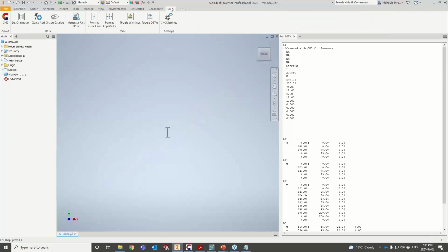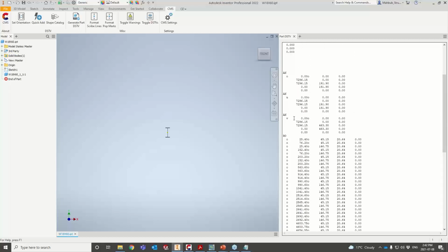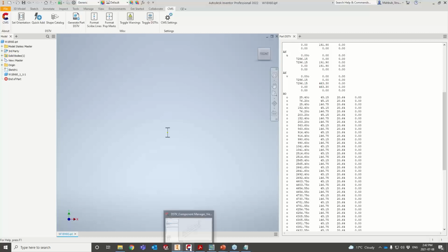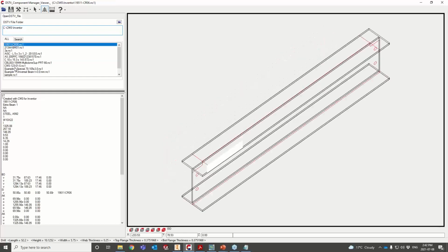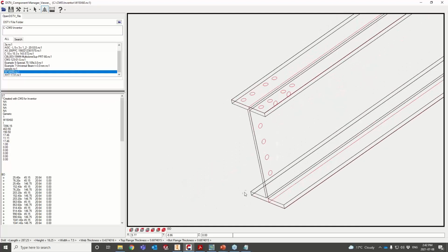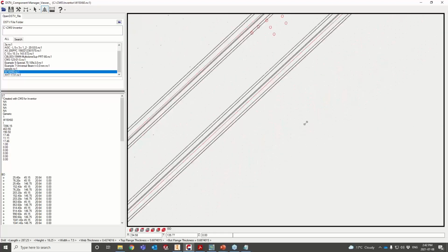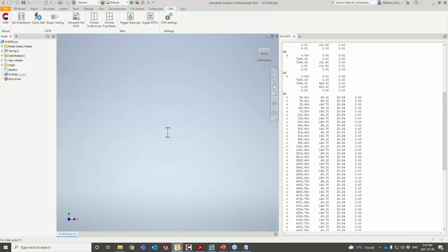So all you have to do is give it the shape size information, because it doesn't have it, right? I have it, so it's 60, enter on the keyboard, it takes it, generate DSTV, and it updates the NC1 file. As you see, it grabs all the details on the drills. If I just try to verify that again, refresh that path to see the updated NC1 files here. So it should be over here. There you go. As you see, it was able to grab all those drills within seconds, and I would say it's pretty powerful for sure.